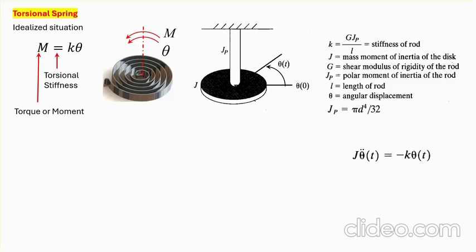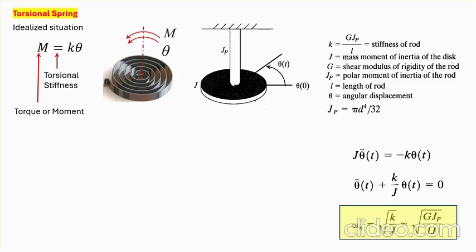Now the vibration, assuming that there's no damping here, in a basic vibration book, you see that the governing equation of motion is this: rotational inertia is balanced by the torsional spring force. If you take everything to one side, this is the equation of motion, which is the analog of m x double dot plus k x equal to 0, except that because we're dealing with torsion, with rotation here, it's not m, it's J, and k is the torsional stiffness. The natural frequency of this is the square root of k over J, no damping here.